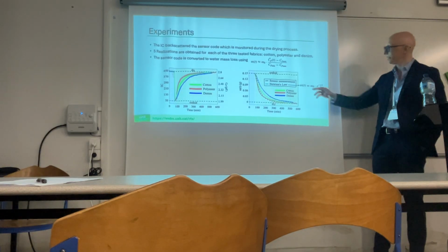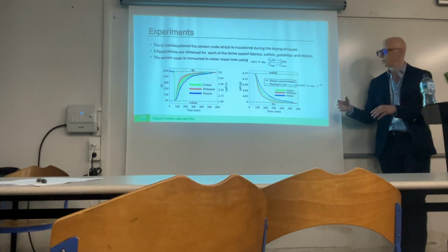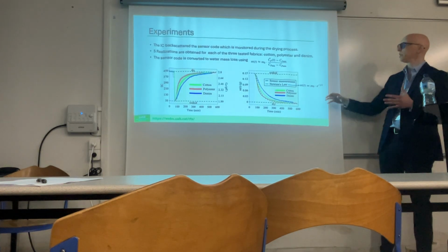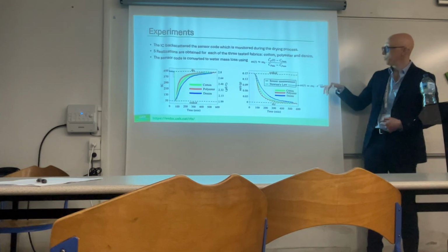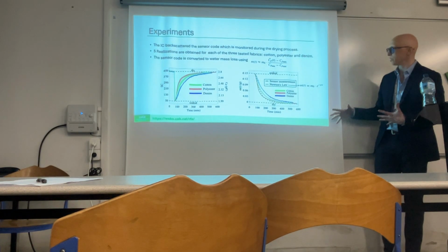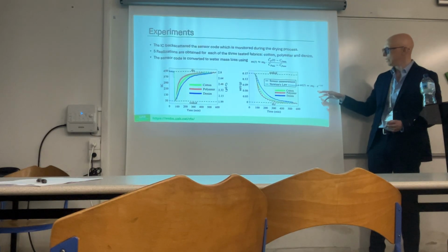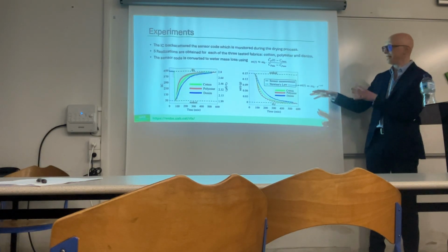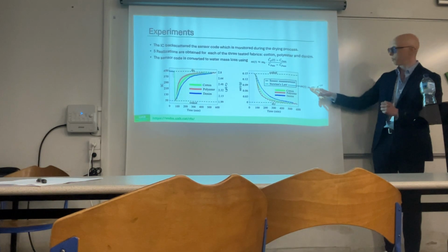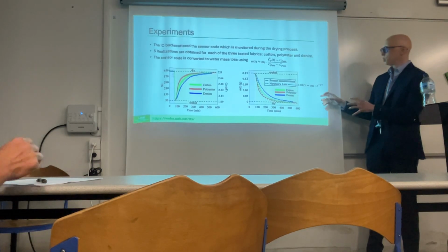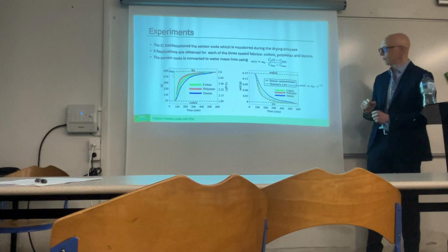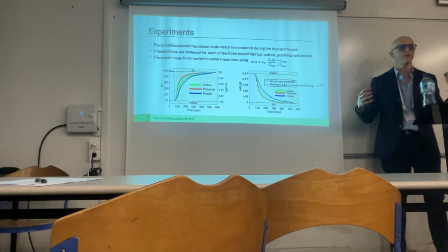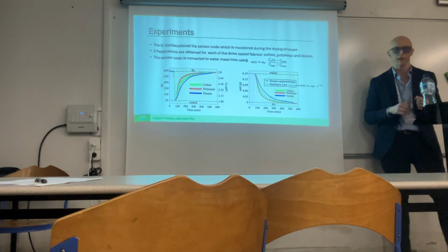Then this is something that we are working on now. We want to calibrate the sensor, and we're using Newton's law of cooling applied to mass transfer, which in our case simplifies to an exponential decay, to fit the exponential parameter gamma, and then compare different methods using this exponential parameter.